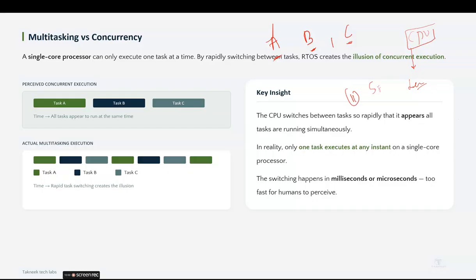Okay, so you might have a phone which is 8 core, we said octa core, right? And your laptop can have 8 cores obviously, and so on and so forth. But for a controller, suppose we have ESP32. ESP32 has 2 cores, right? And suppose we have STM32, the version that we will use in the course, the hardware that has a single core. Okay, so with the single core, there is a problem.